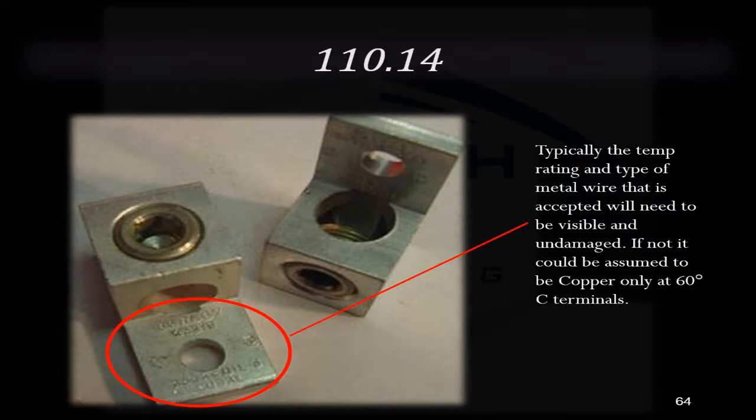Typically the temperature rating and type of metal wire that's accepted will have to be visible and undamaged for the AHJ to accept it. If it's been all scraped up and it can't be read, then it's most likely going to be assumed to be copper only at 60 degrees Celsius terminals, which is the safest rating that an AHJ would be able to give you.